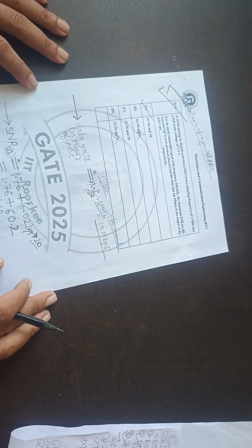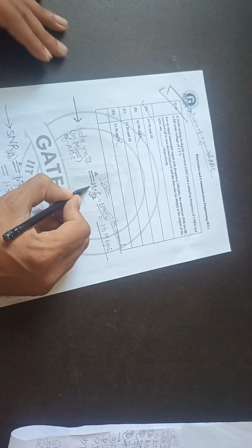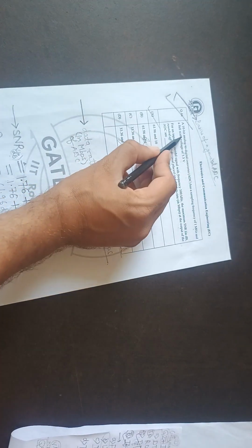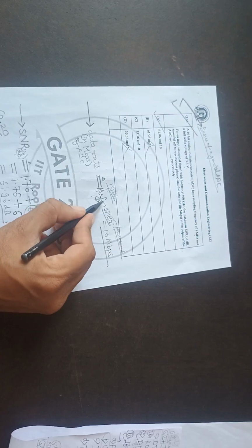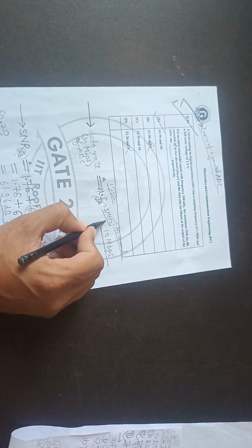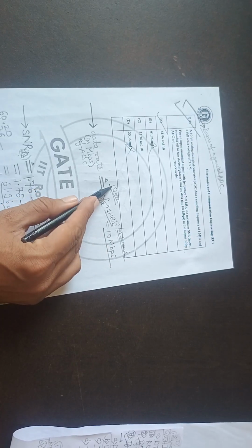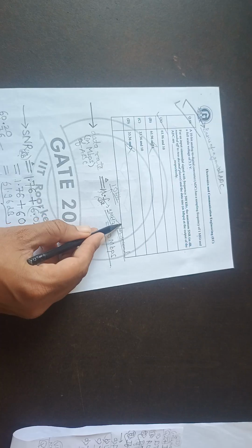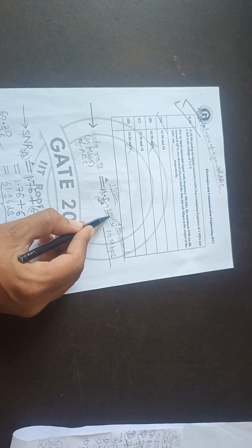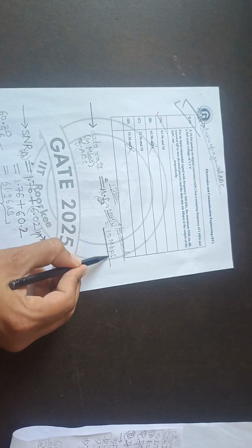So here we can use the basic formula. The data rate in Mbps of the ADC is n times fs. n is the number of bits, so it is a 10-bit ADC, so n is 10, times the sampling frequency of the ADC, which is 1 megahertz. Hertz is per second and this is mega, so 10 megabits per second. 10 Mbps is the data rate of this ADC.